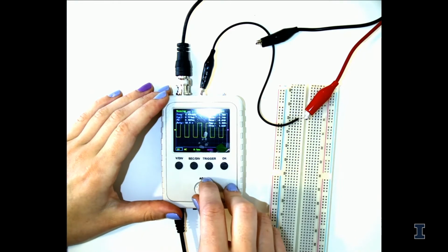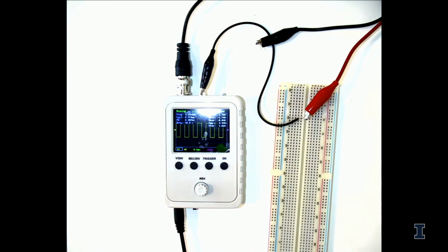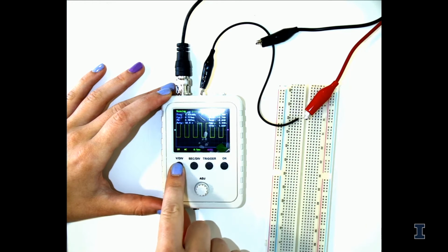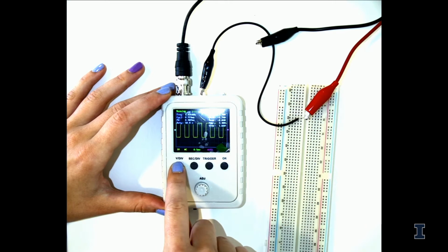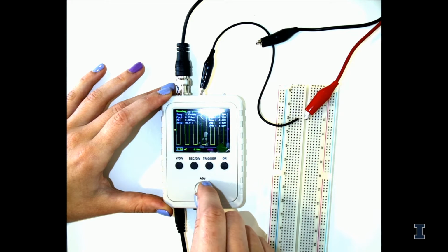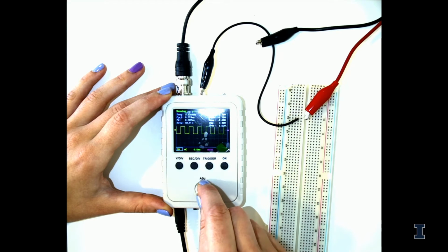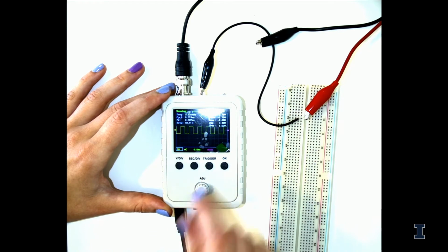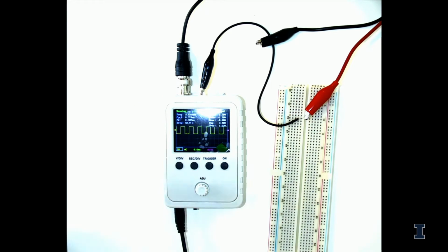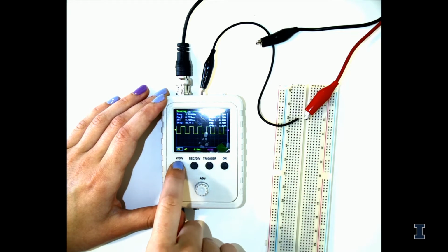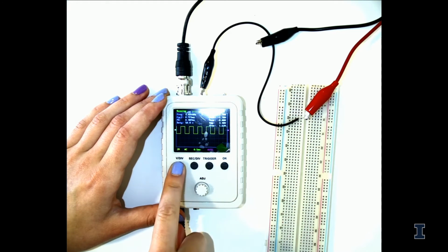All right, so let's say your signal wouldn't fit on this screen. This one is a pretty nice signal for example purposes, but how you can adjust the oscilloscope is on the left. If you press V/div, this is your voltage increments. If you press it so that it's highlighted, you can then use the knob to adjust what your increments are going to be. Up and down, you can see that the value is changing. Right now we're at 2 volts. You can see it's still the same signal, just on a different scale. When you're done adjusting your voltage, you can just press it again, so it's unhighlighted.